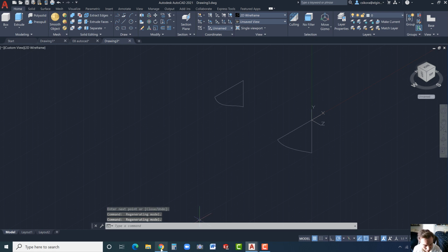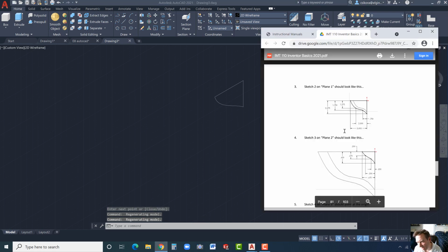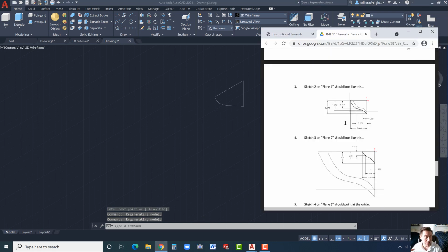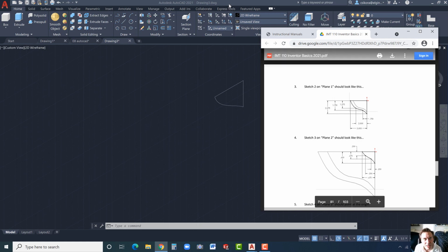Now the next one is going to be 8 inches, and this is where if you're going to make an elongated hull, let's say you're going to make a cigarette boat, like one of the fancy speedboats, and you want to make that hull longer, this is where instead of 8 inches, you could span it out maybe 12, and it's going to make a nice long hull. All right, now this next one's going to be very small, 0.6 by 0.675. So let's do 0.6 by 0.7. We'll just round it off.